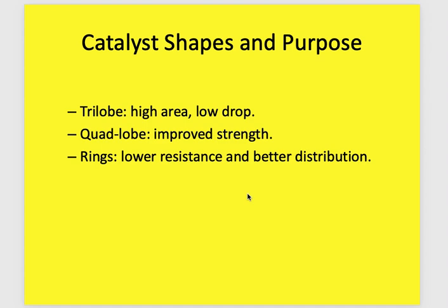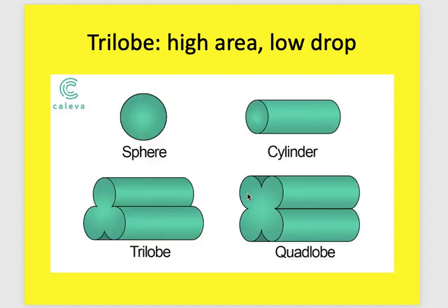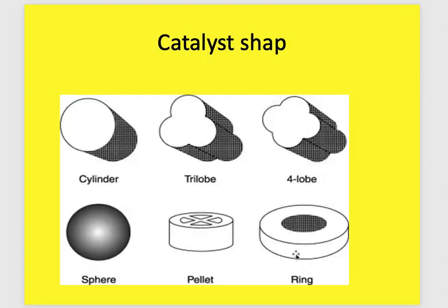What is the shape of this type of catalyst? We will see together that this is a sphere ball catalyst. This is a cylinder shape catalyst. This is the quad-loop or tri-loop, and for each one of them there is a selectivity, and you have to refer to the pressure profile and the contacting area to select the suitable type of catalyst for your case of reaction. Okay, so you may choose the cylinder or tri-loop, maybe the quad-loop or ring, or even sphere catalyst shape. Okay,